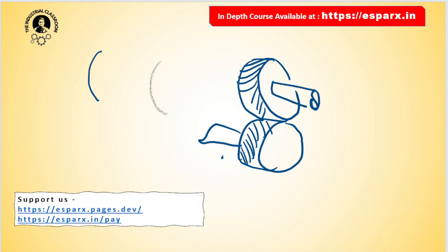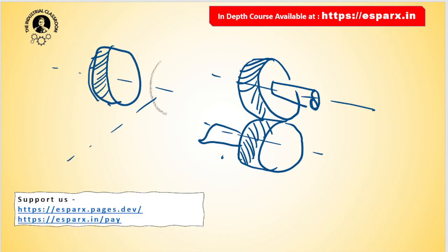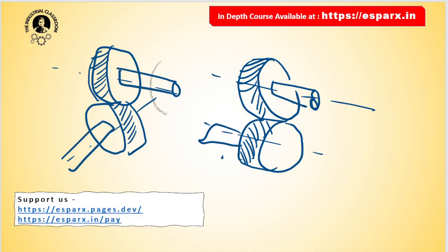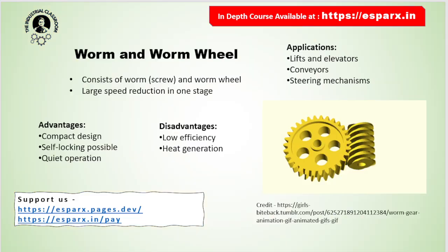But in spiral gear, these are parallel shafts, but here these are not parallel. I have drawn the same gear here, this shaft, and this is at some other angle. So you can see that both the axes of the shafts, in case of helical gear, are parallel with each other, but in spiral gear the shafts are at different angles. This is the only difference between the helical gear and the spiral gear. I don't have the exact model of the spiral gear, therefore I have just made you understand like this.